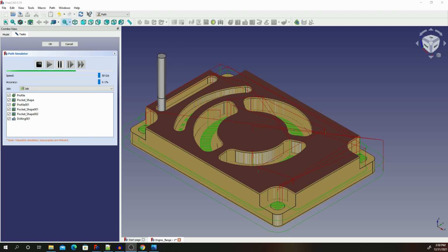So just to be more cautious, I've worked with CNC machines, and you can easily break some tools if you've done the wrong coding. So just make sure when you're taking this code and you've designed it in here, check it out, check the codes, reduce the feed rates on your machine, and just maybe try a demo cut to make sure everything is running okay before starting to cut metal.